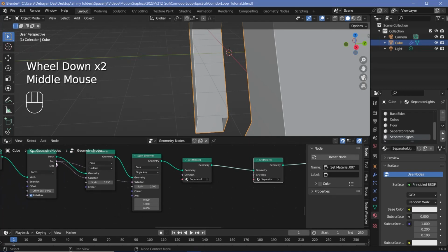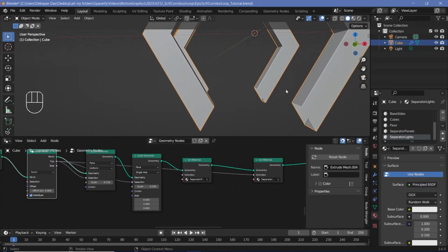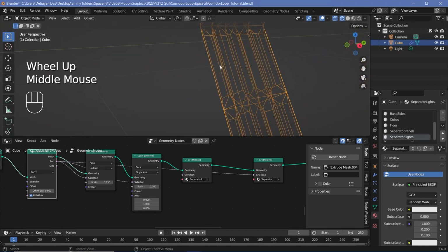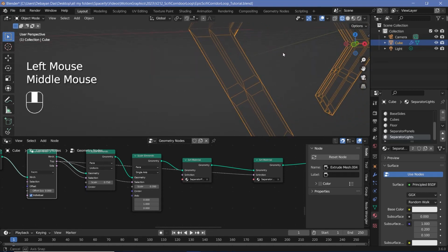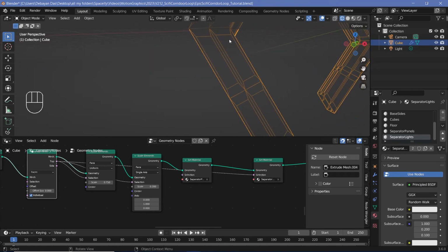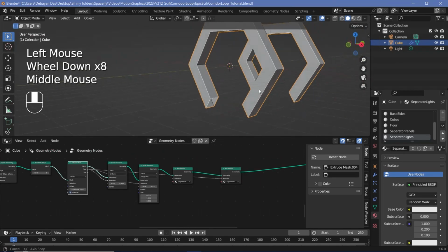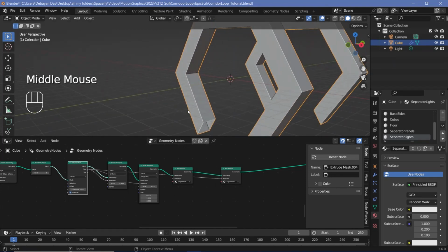Now we could directly use this top selection and plug that in, but the issue with that is that we have a lot more lights that are going to be created, because if we were to go back to wireframe view, you can see there were extrusions that occurred even on these side faces. So these side faces would also be lit up. Let's switch off transparency so that you can see only the side faces, and you see there's an extruded face over here. So if we were just to use this top selection, even this face would be lit up, and I don't want that. I want only the faces that are towards the inside to be lit up. So for that, we can go ahead and check for the normal direction, just like we did before. We need to make sure that it is not pointed in the Y direction.